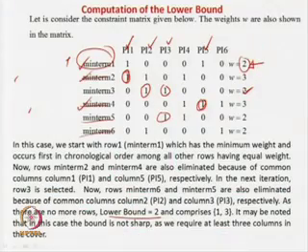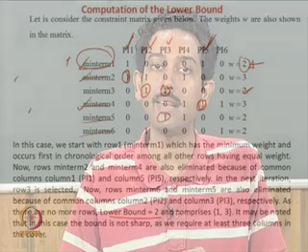Obviously, you are going to get a lower bound, but not any positive delta. Why is there no positive delta? Because you are saying that I am covering this row by Pi 1, and automatically another row gets covered. But the idea is that by Pi 1 you can either eliminate row 2 or you can eliminate row 4, but not both. That is very much clear over here. If you take Pi 1, you can cover min term 1 and min term 2, and if you take Pi 5, then you cover min term 1 and min term 4, but both are not going to happen. But in the heuristic you are saying that in one go I am covering min term 1, min term 2 and min term 4.